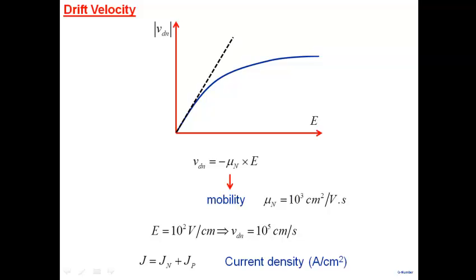And so the equations that I've talked about hold for holes as well. For example, I can write the drift velocity of holes and plot it as a function of electric field. I'll get a similar relationship, vd equal to, and I can talk about the mobility of holes, just like I've talked about the mobility of electrons. So I have electrons and I have holes.